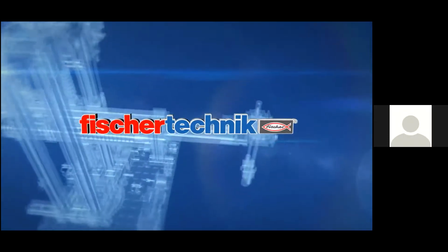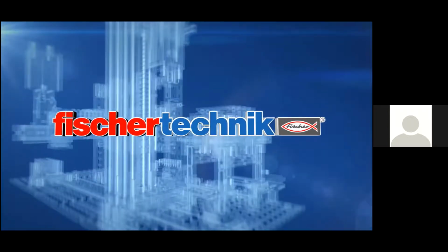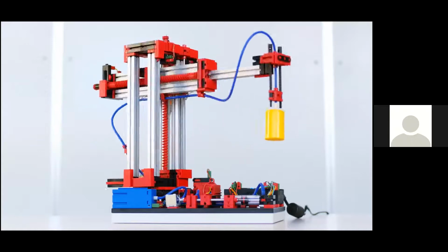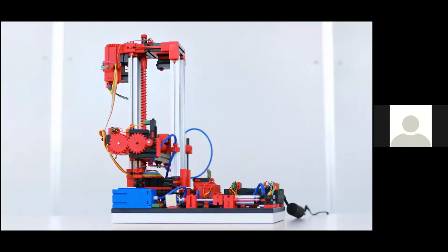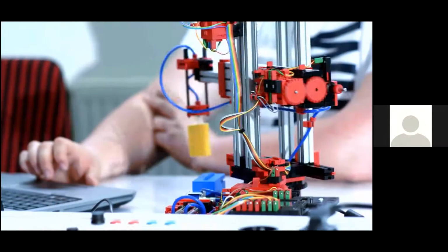Now, as you're going to see, the vacuum gripper is a 3-axis robotic model with a vacuum gripping device. The model is designed to precisely pick up and position workpieces in 3-dimensional space. The model includes 3 encoder motors, 3 push-button limit switches, a vacuum suction device, a compressor, which is the blue brick component you'll see in the video, and a solenoid valve.